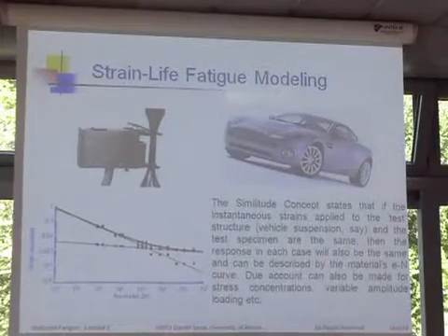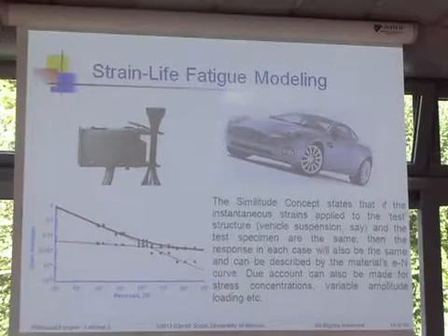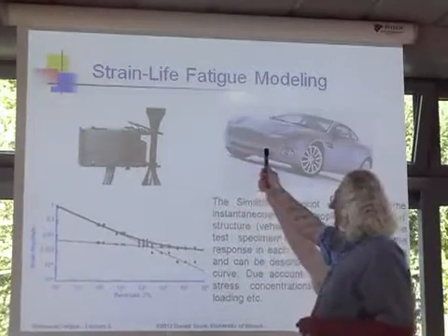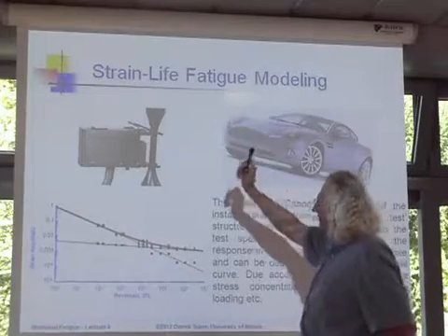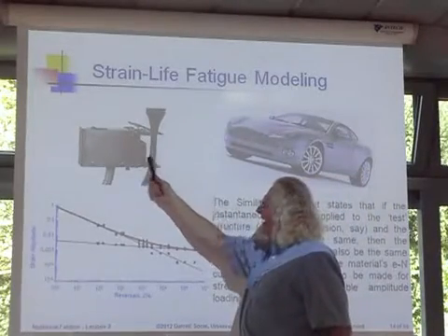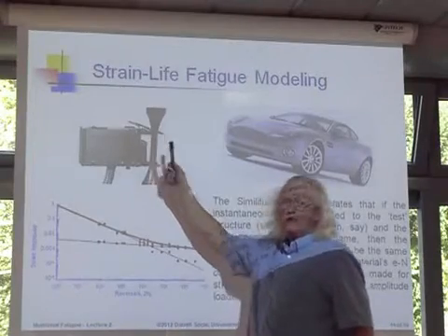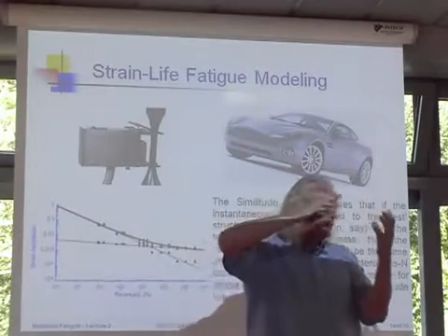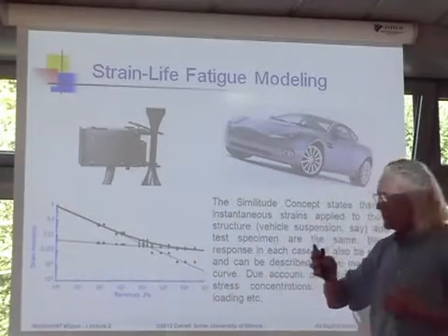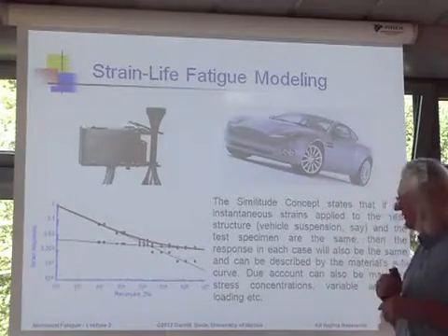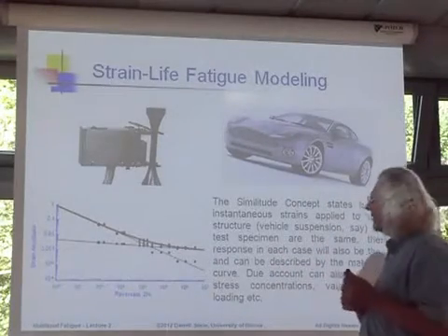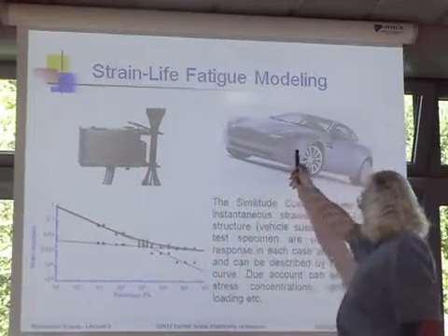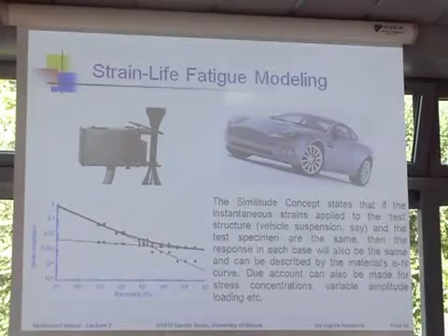And those are parts for which we have a lot of plastic deformation. And again, what we're really asking is not whether this resembles this in terms of size or shape, but in the physics. And the physics here is one where, because I have plastic strains, I will nucleate small microcracks early on in the lifetime. These small microcracks will grow and interact with the microstructure, and eventually they will turn into big cracks of several millimeters, and when they do that, they will rapidly go to failure. So when I have this view of the physics, what parts have that failure physics?